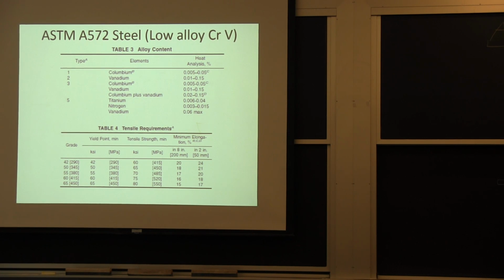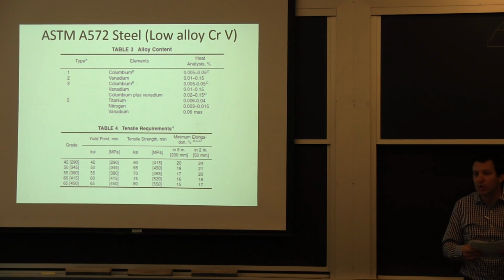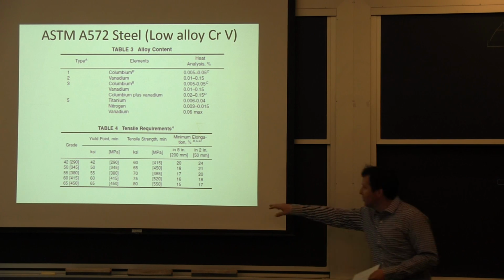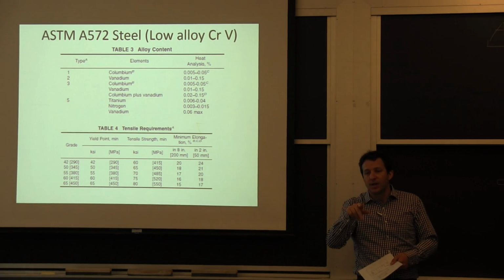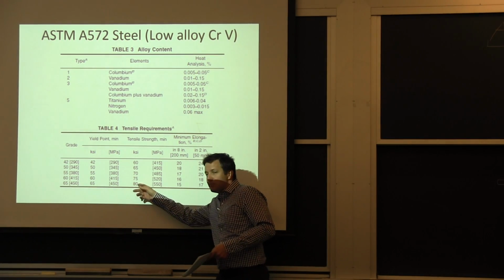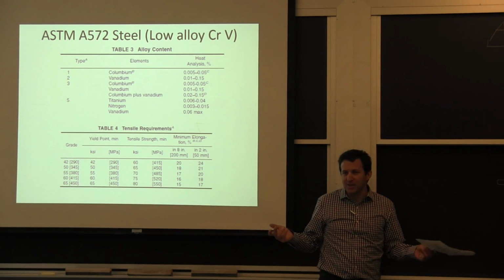The ASTM specs are 10 pages, and they call for other specifications in terms of basic requirements, how you're supposed to measure things, how you come up with these properties here. If you saw that dog bone sample, that's part of this. This is not something where I machine a sample the way I want, get the number, and say, oh, it meets ASTM.